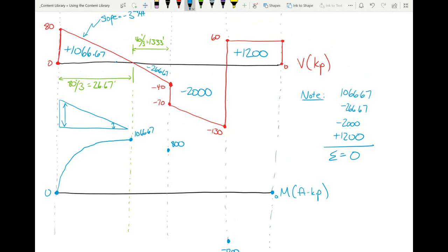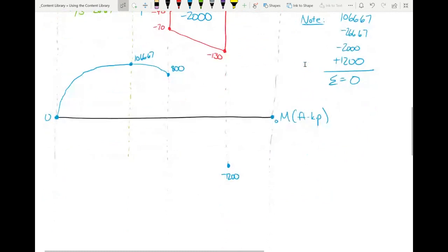Similarly, if you look at the next region on your shear diagram, see how that triangular region goes from a really, really tiny value of shear to a bigger value of shear. The shear diagram goes from a little to a lot. So we're going to go little to a lot. I'm sorry if the line's getting a little wavy on me. It should sort of look like that. What we're trying to draw here is a parabola. That's the best parabola I can draw. My art skills are horrible.